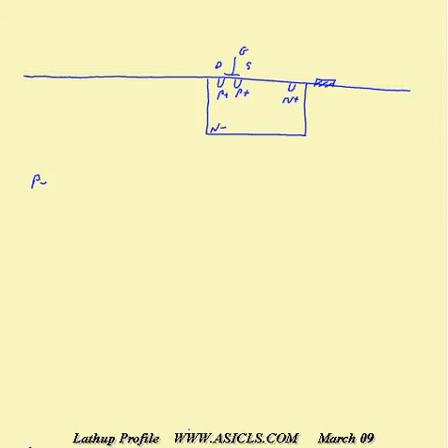up to VDD. Next we'll switch to the N-type transistor, which we define in the P-well, or substrate. We do this with two N+ implants, and again we form the transistor by bridging the two N+ implants with the gate. We mark this drain, gate and source.